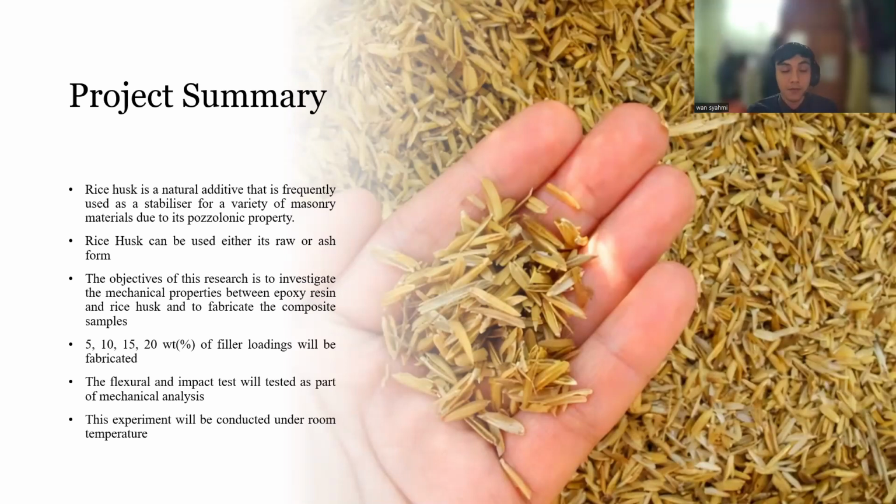The objective of this research is to investigate the mechanical properties between epoxy resin and rice husk and to fabricate the composite samples. 5, 10, 15, and 20 weight percentage of filler loadings will be fabricated. The flexural and impact test will be tested as part of mechanical analysis. And this experiment will be conducted under room temperature.